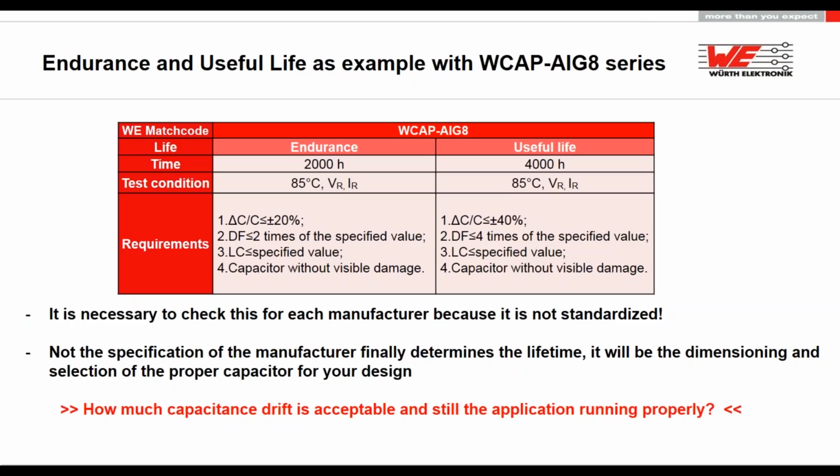It's not the death of the ECAP. We are talking about a degradation process. And this is a very important thing you should keep in mind, because as you can see, we also have a useful life statement. This is given with plus minus 40%, and this will be 4,000 hours. And as I said, it's not the death, it's a worst case scenario that we have.